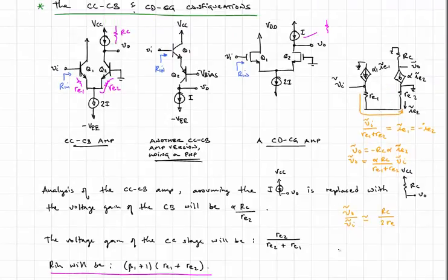So the voltage gain is essentially just a factor of 2 off of the voltage gain that we would expect from a common base amplifier: collector resistance divided by the incremental emitter resistance. But again, there are some significant differences in this case. The input resistance is beta plus 1 higher than it would be for a common base amplifier alone.